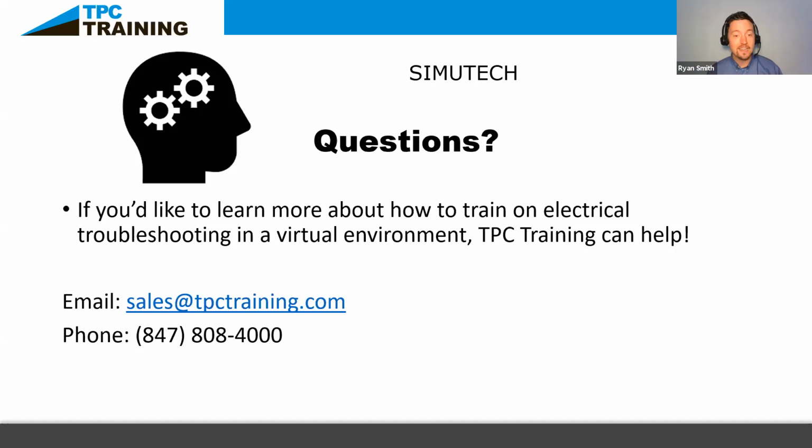I would comment that sometimes in the electrical troubleshooting class, what should you read across the coil for voltage if it's working properly? That's a very interesting question, and it's the same answer as almost any electrical question. It depends. And in our case, it depends a lot on the size of the relay and especially the voltage that the coil works on.